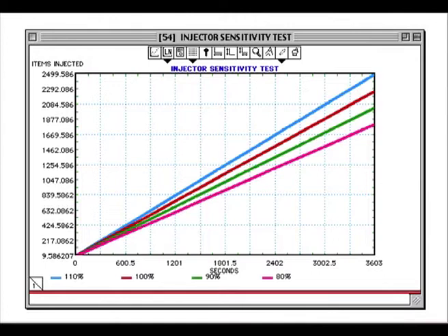The operation of the injector is this. The injector starts off empty. At its lower speed it loads on one parcel, then a second parcel. It then checks that the belt is free in front of it. It then ramps up to belt speed and injects the 2 parcels onto the belt. The next piece shows a short video showing the warm-up and the output of this Teleflex model.